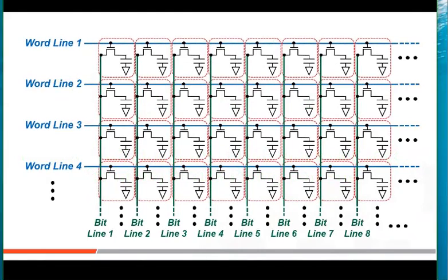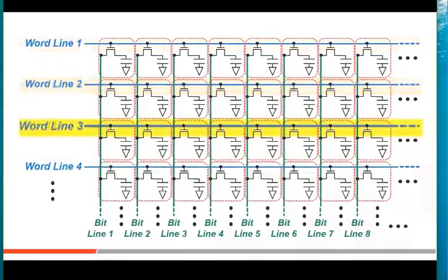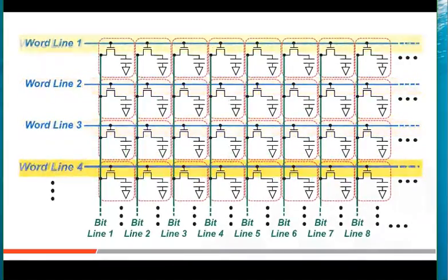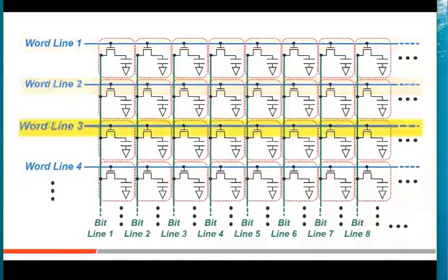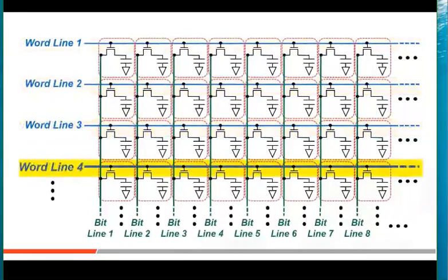The trick is to have the cells refresh themselves every time they are read. Then just stepping through all the address word lines and doing a read-like command sequence at least 16 times a second for every word line will keep your DRAM data just like you wrote it.